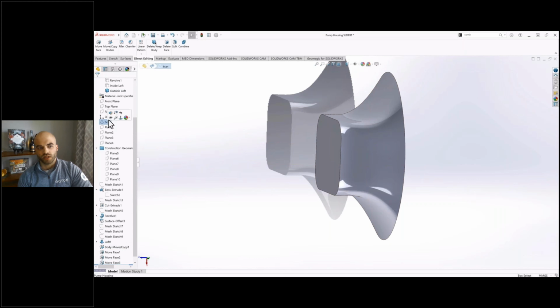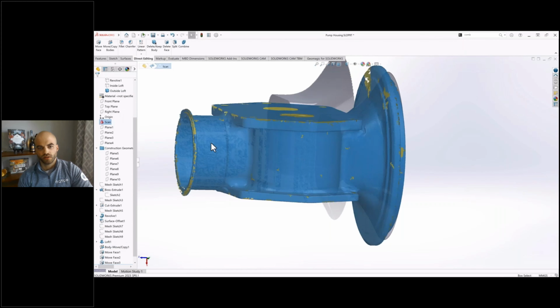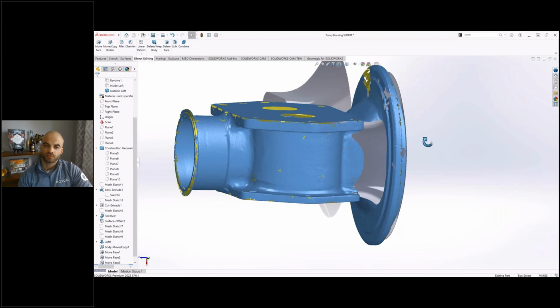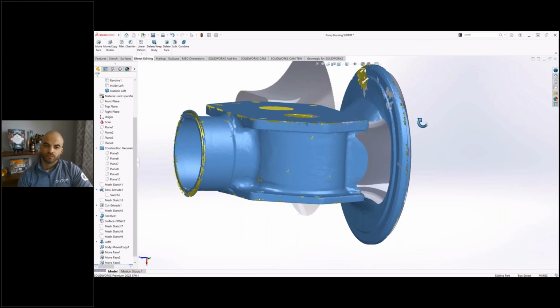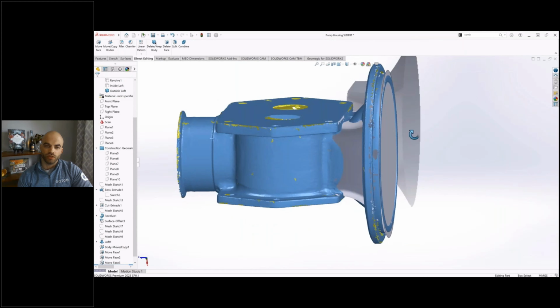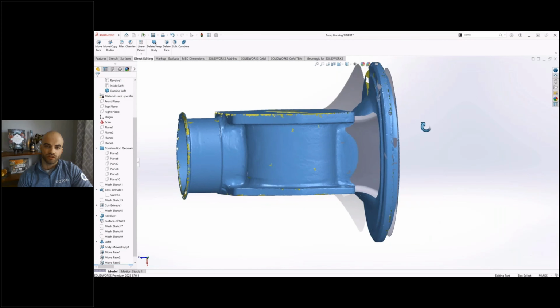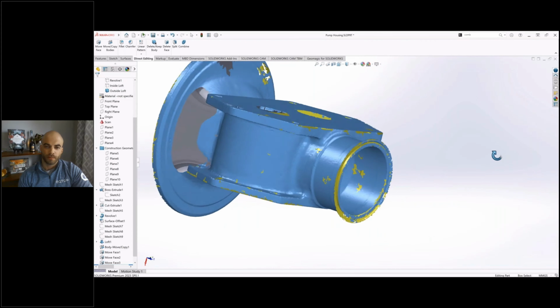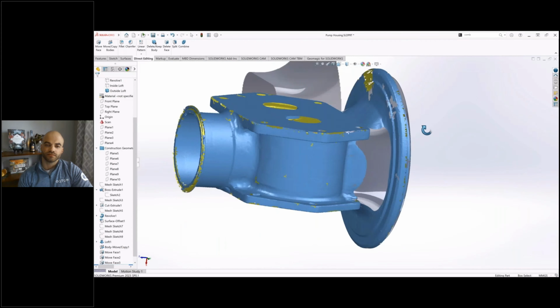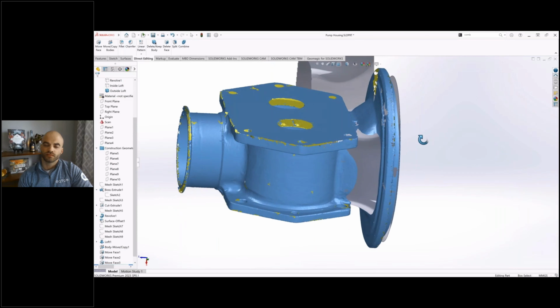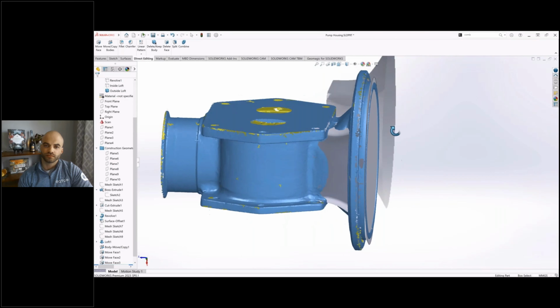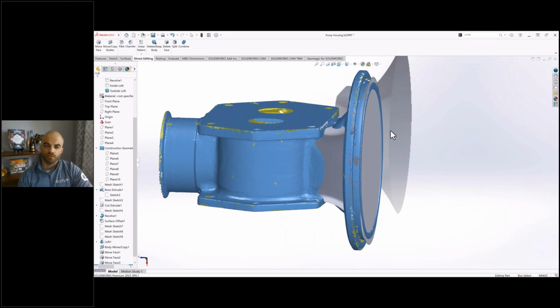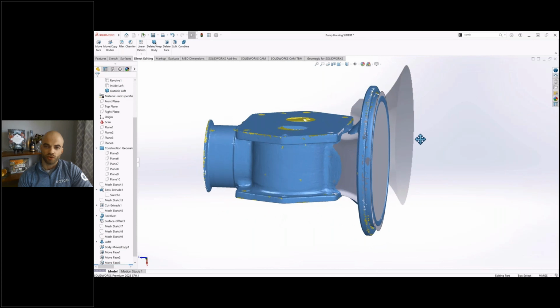So there's our outside loft finished. And we should be good to boolean. I think I might tweak it just to move one face a little bit further, but at this point we're almost ready to boolean. Oh, you've got to trim that outer lip on the front plane as well. That's poking out too far.